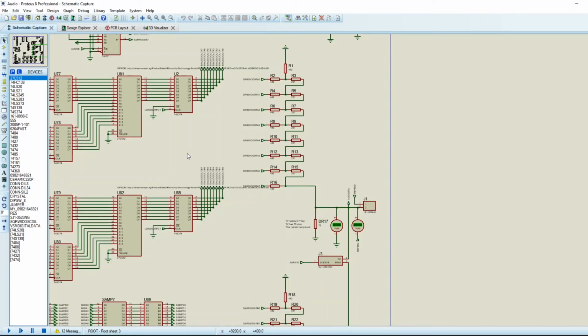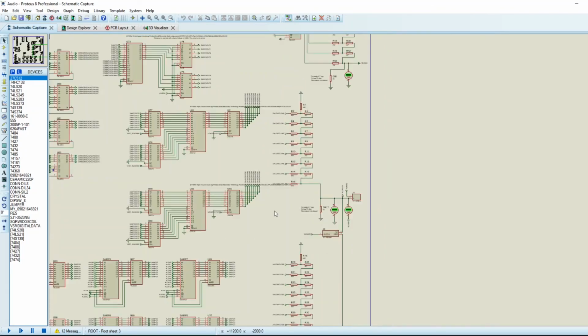I mean, I am using this style of resistor ladder arrangement for the video board, and it does work reasonably well, but that was only generating positive voltages in an analog range. This is a negative to positive voltage, it's RMS voltage. So we'll see how it goes. I'm going to be very interested to see how that works out when I actually get a PCB.